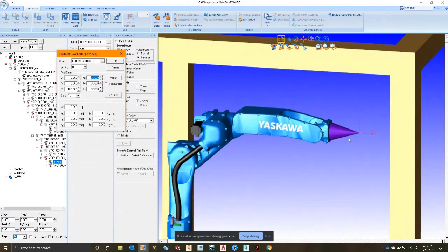for the teach point. So it's angle, the RX, RY, RZ, and its position, X, Y, and Z. Down here, this is the mechanical data. This is very important for two reasons. In the simulation, it's important for cycle time. This is a GP25 robot, and I gave it no tool weight. So it's not thinking there's zero tool mass. It uses default parameters. All our robots do this.